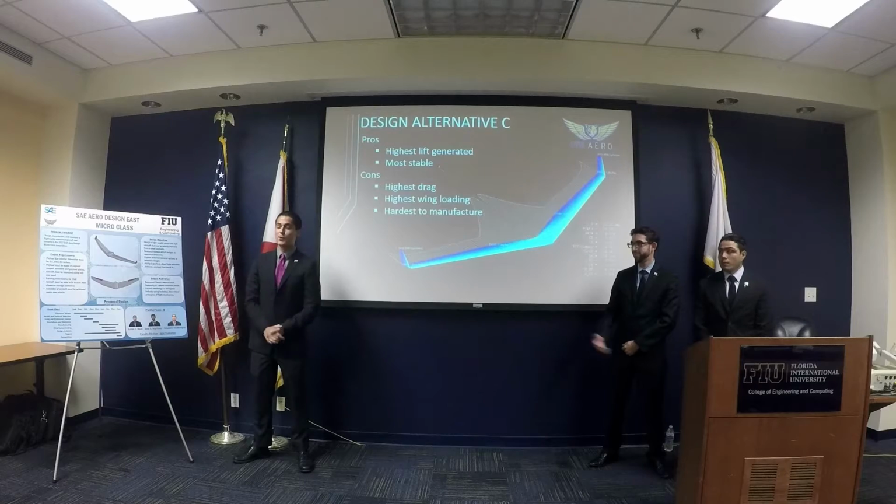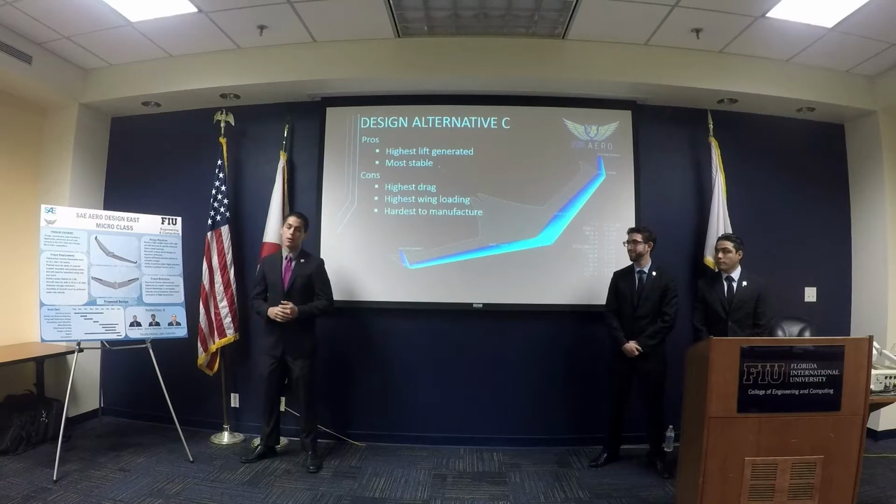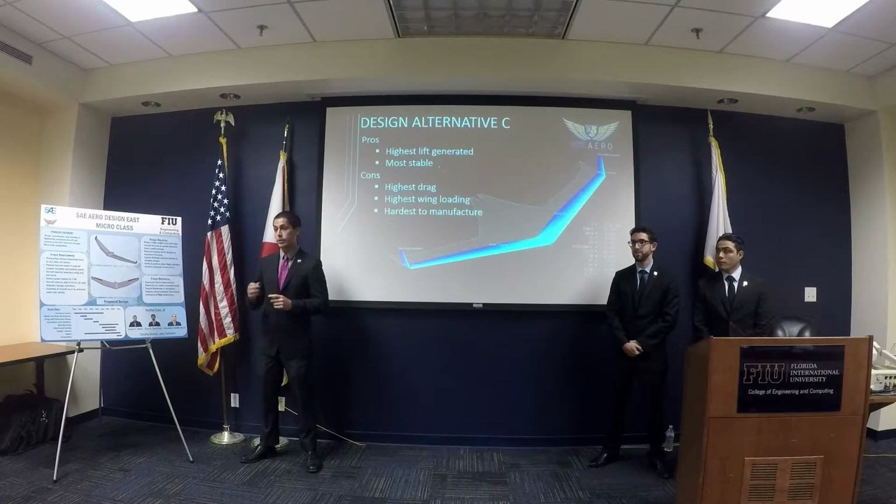Well, that's where the engineering comes in. Whether we're adding a stress skin to this, made out of Ultracote or carbon fiber, or we're just using a balsa spar going down the wing. Balsa would just be one of the components in the aircraft. We'll most likely be using carbon fiber ribs with some sort of balsa insert inside. But the whole point is to control these 2 uses of carbon fiber and balsa to make it as light as possible. This is not to say we're going to construct the wing only with balsa. It is one of the materials we are using. If we want to construct with only balsa, the option is there. But since balsa is weak, we are not planning on doing that.